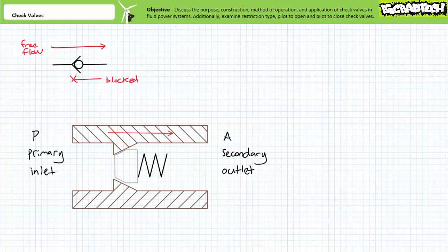The schematic symbol for a check valve shows a ball on a seat because old school check valves really did use a ball rather than a poppet. The ball fell out of favor because over time, the ball would wear a groove in the seat and would function perfectly well until someone took it apart. If the individual responsible for reassembly failed to put the ball perfectly back into the groove, the check valve wouldn't seat properly and allow a degree of leakage in the ordinarily blocked direction. For this reason, most check valves employ a self-guided poppet that easily seals even after reassembly. Regardless, the schematic symbol still uses the ball and seat symbol.